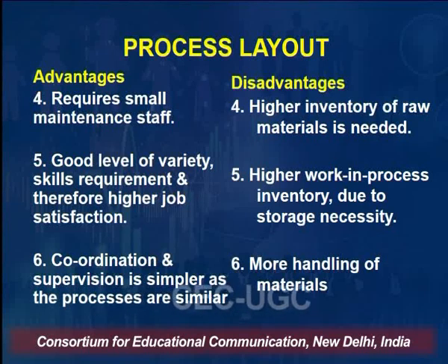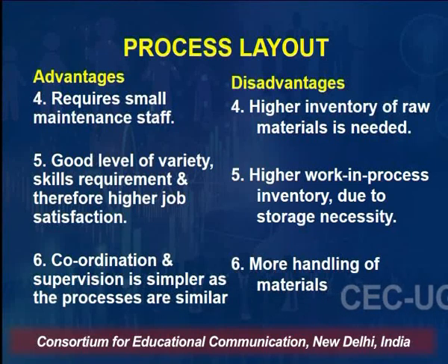It requires a small maintenance staff, then a good level of variety and skills requirement, and therefore higher job satisfaction to the people. Then coordination and supervision is simpler as the processes are simpler. And disadvantages are higher inventory of raw materials is needed, higher work in process inventory due to storage necessity, and more handling of materials. So whatever we are saying is being validated by our slides. So we are saying that what were the advantages of product layout become the disadvantages of process layout.